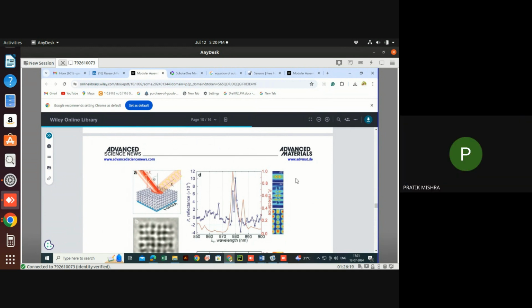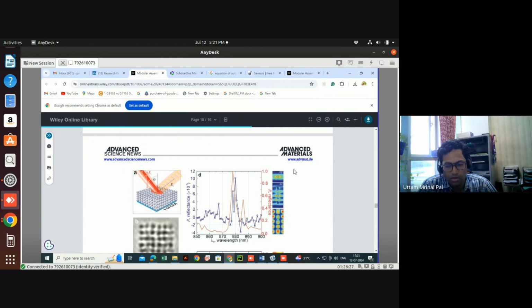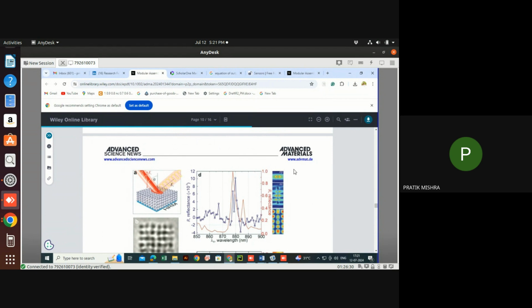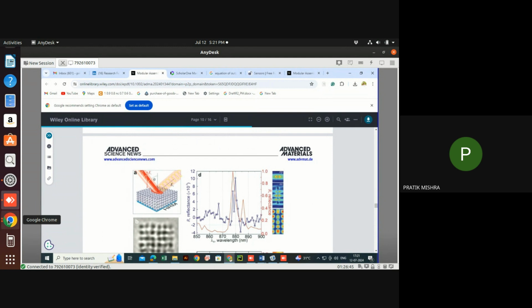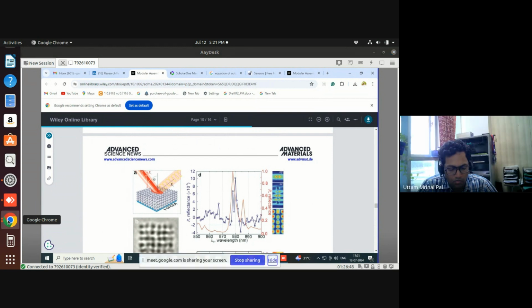My question is, instead of taking port 2 at the bottom position, if I take port 2 at the same boundary? No, you don't need multiple ports on the same boundary, unless there are some higher order modes being generated. If you apply a single port at the top and apply PML at the bottom, then you can get reflectance, like what I think Kavita was showing yesterday. I don't know if you've seen that. If you apply a port at the top and don't apply anything else, whatever is just passing will be absorbed at the bottom.